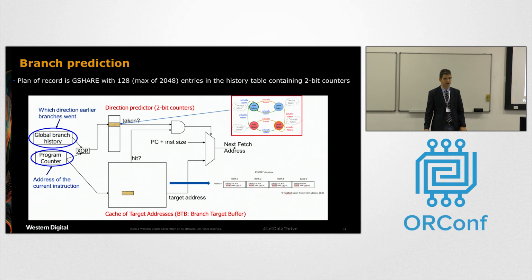Normally, you would go for G-share because it gives the best balance in terms of size and what it can do with realistic code, meaning it can get you into sort of a 94-95% range, depending on the size of the register. And this is where the CoreMark score changes. If you go with 2048 entries in the BTB table, you can get really nice CoreMark results, but you will also consume a lot of your area. So that's kind of a tuning parameter: what's really needed for the application, what kind of firmware application is running, etc.